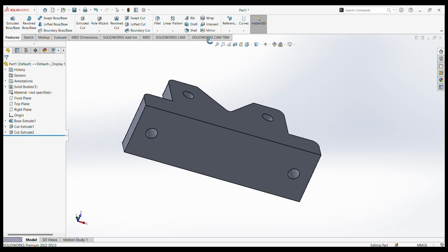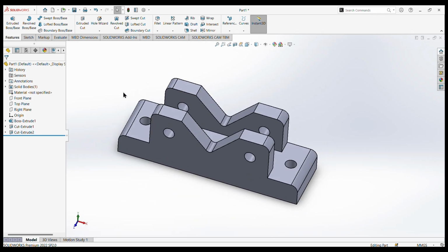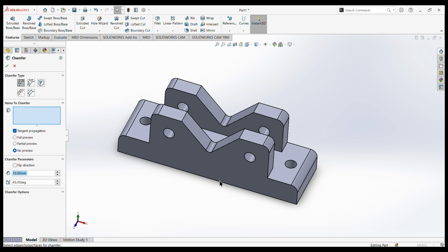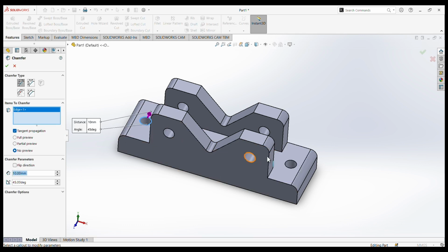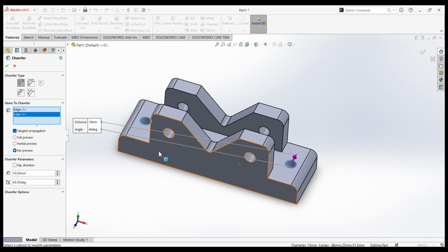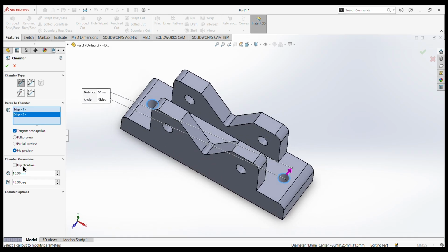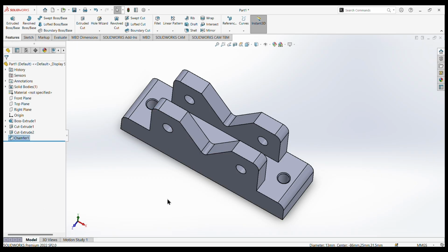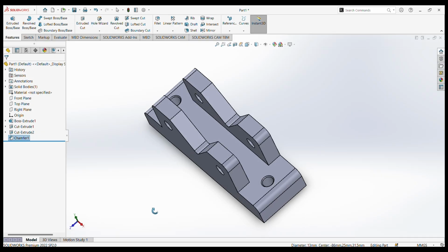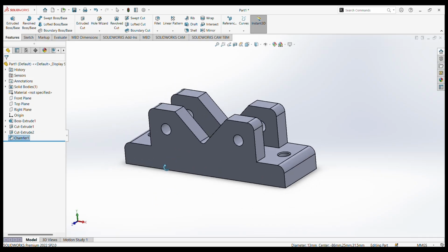now the one command remaining is that we apply the chamfer. Select the chamfer command and select the edges, this one. Okay, and now the chamfer is 1 millimeter distance and angle is 45. Okay, now look here. Okay students, now our whole part is ready.